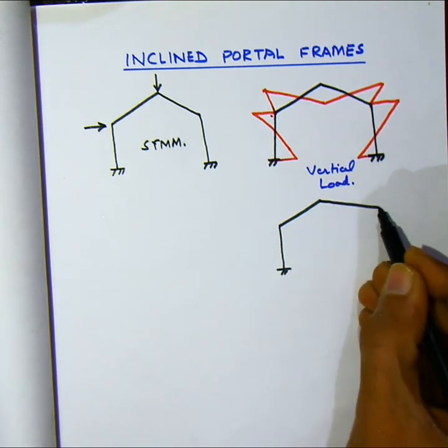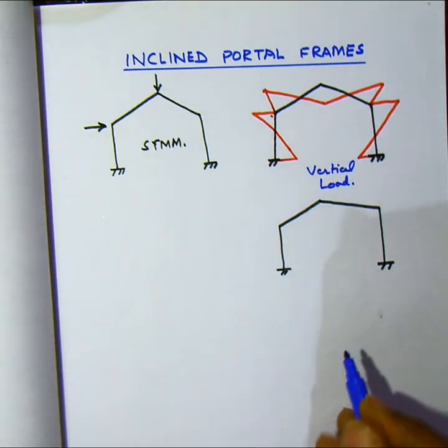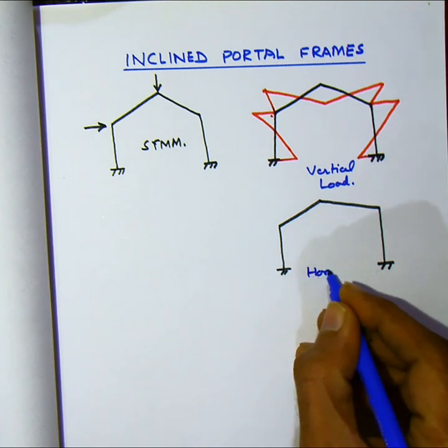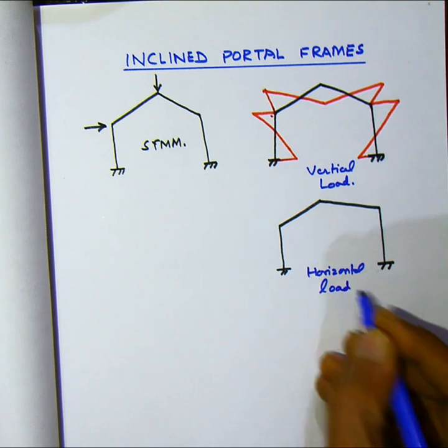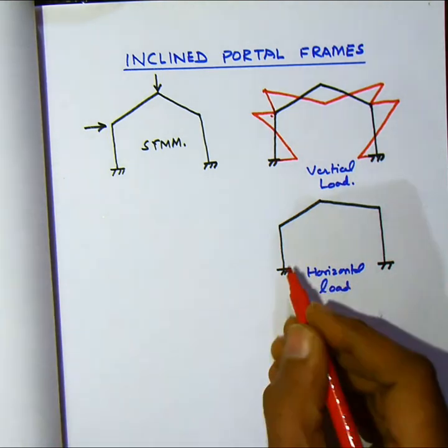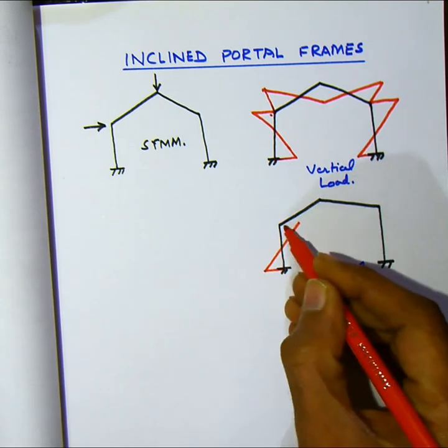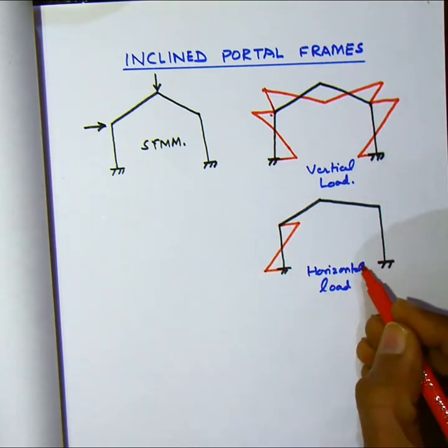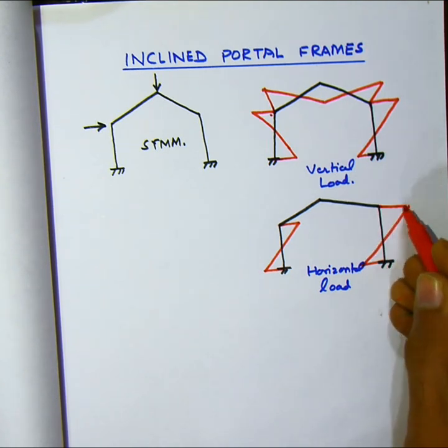That is, at the crown, the peak will not be there, it will be just zero bending moment at the crown. Okay, so under horizontal load, both the columns will have identical bending moment diagrams, unlike the case of the vertical load, and the bending moment in the case of the top beams will be zero at the crown.